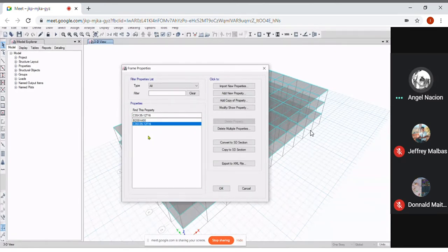So that I can easily recognize what rebar I put there. You can copy how I name columns. The first one is the size, C35 by 35, meaning 350 by 350, and 12 diameter 16 means that there are 12 diameter 16 longitudinal bars.